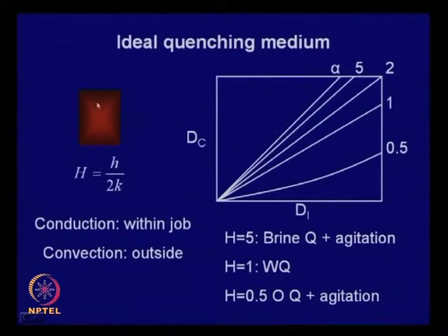So, that means as you quench, the heat transfer is infinite, and the surface immediately comes to the temperature of the surrounding quenching medium. That is the maximum that we can think of, but we will see a little later that it is far from reality. Nevertheless, in many cases one does define such cases, a hypothetical quenching medium where H is infinite.